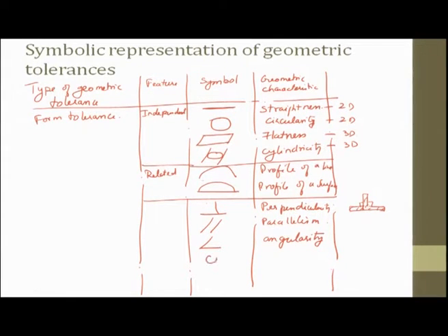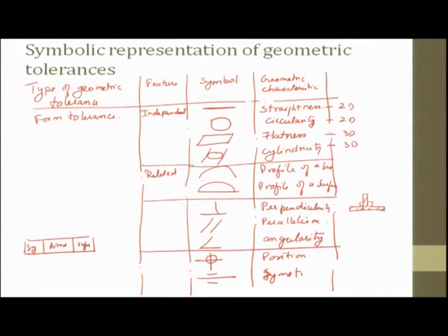then we talk about position. So if you go back and see, we drew this, right. Here we talk about a symbol, then some dimensions, whatever it is, and then we talked about this being with respect to some reference. So this is one row, and we will have 3 columns. They will put the symbol here, then they write what the dimension or deviation is, and then they also talk about this. So, you can have position, you can also have symmetry. Then you can have concentricity, 2 circles, this is concentricity. So, these are some of the symbols which are used.